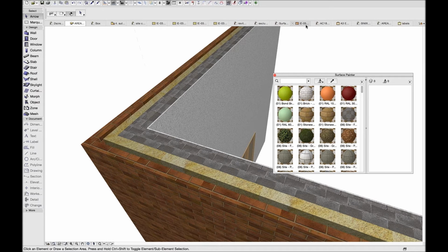This is a complex task for any BIM application, as the reference planes for the area calculations are defined differently for every composite structure. For instance, the insulations are typically calculated in the center of the insulation layer, while the internal plaster area is measured at the internal surface of the wall.